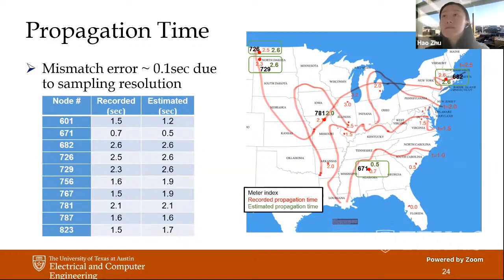But then for this short time scale problem, there are also a lot of effective control strategies, like a wide area stabilizing control, or even local frequency control. So we can use this data-driven method, say that I want to change some control parameter setting and see how it would affect these short-term propagation effects. So that would be very helpful for designing immediate fast control actions.